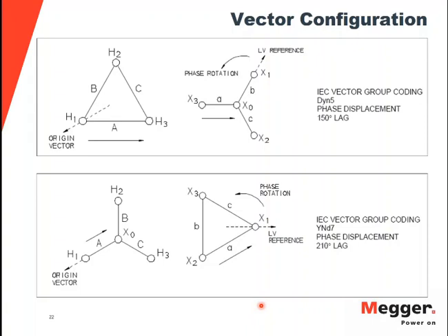H1-X1 and so on? That's a very good question, and with the limited time we had, we were not able to go that in depth. But think about this one, that you have a Y winding, and I'm assuming you're talking about winding resistance. So if you have a Y connection, if your auto transformer and Y connection, you can either measure from H1 to H0, or you have the option of doing H1 X1 and then X1 X0.